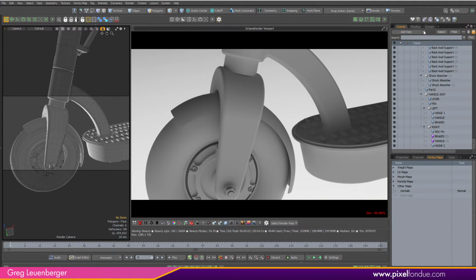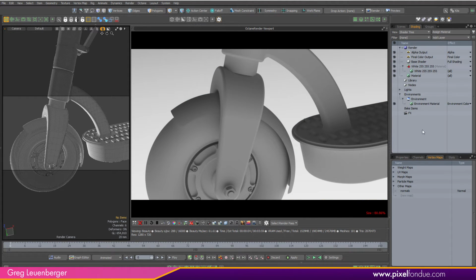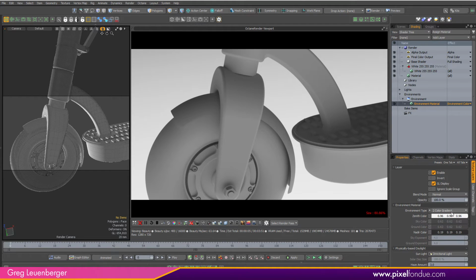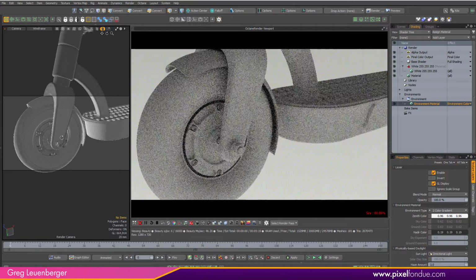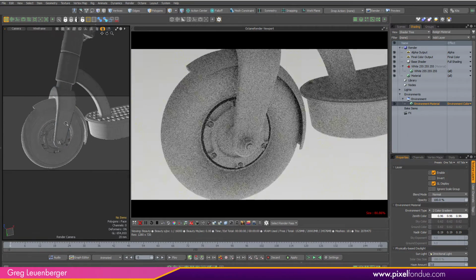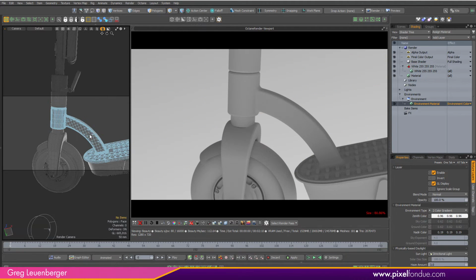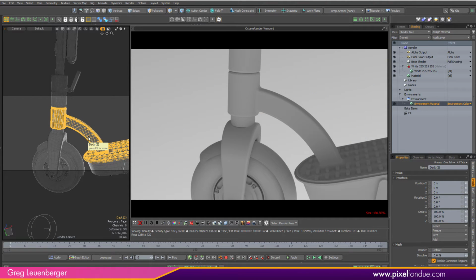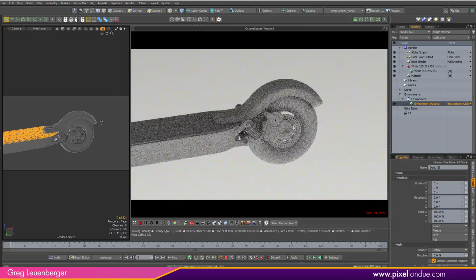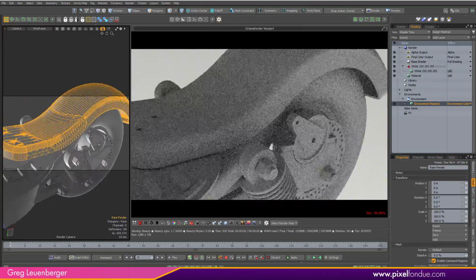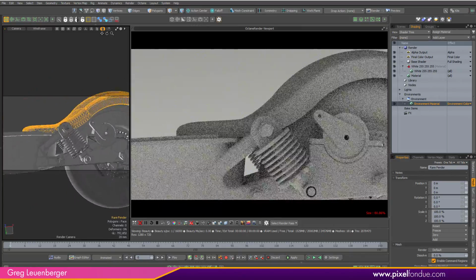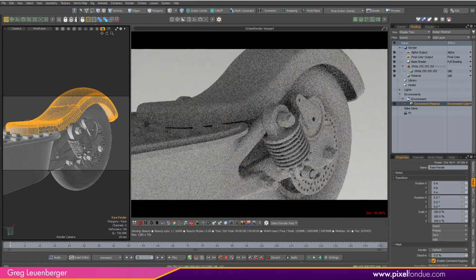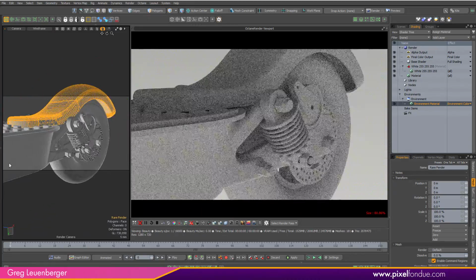It's got my environment background on here. Again, you never really know what you're going to get. Oh, it's okay, a 4-color gradient. That's not bad. So yeah, the geometry is looking good. The default settings were fine for the tessellation. You're not going to get quads, but honestly, you really shouldn't need them if you're just doing product rendering or general mechanism of action animation. If you have tubes and things like that that need to be deformed, you're generally going to remodel those in MODO anyway and rig them up. And sometimes people are obsessed with having quads and UVs and everything, but you really don't need that.